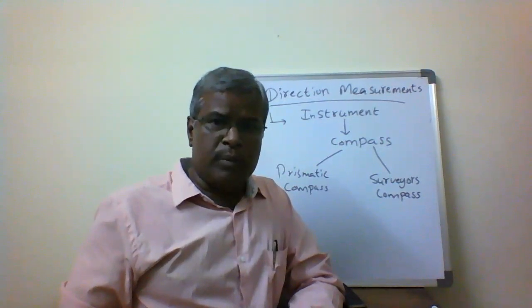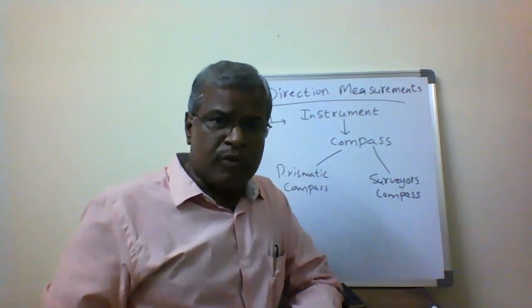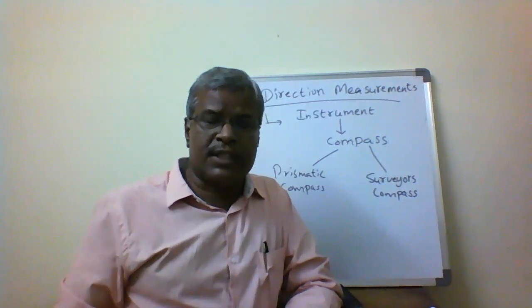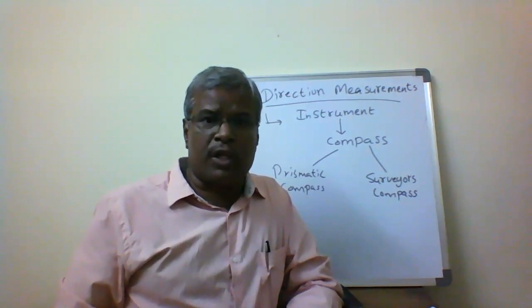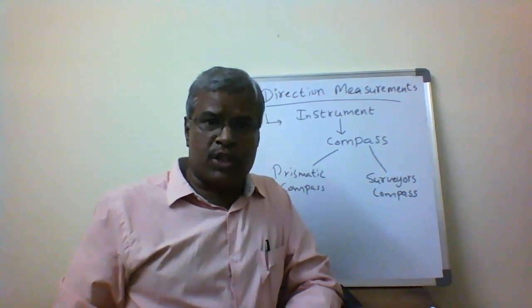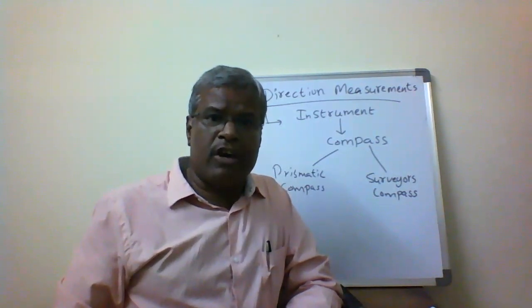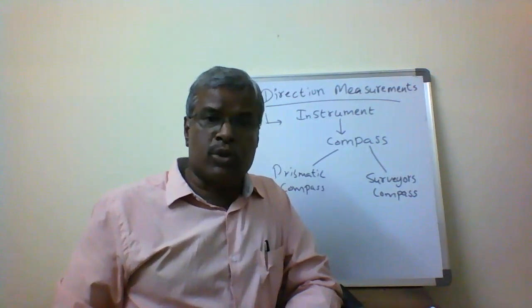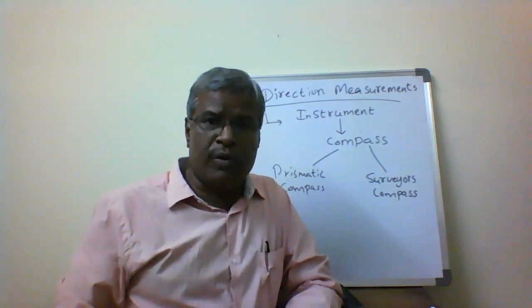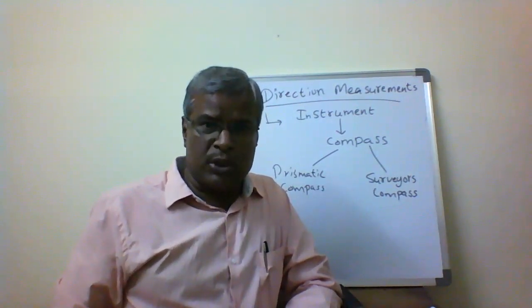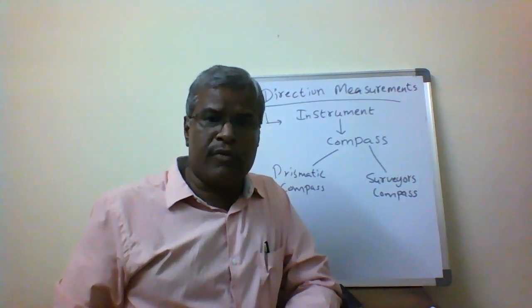Now we'll go one by one through compass surveying. We prefer to use it for a large area to be surveyed. Previously we discussed chain surveying. Chain surveying is used for smaller boundaries with no disturbances, because the instruments are just a chain and tape, and it suits flat terrain. If you go for larger boundaries, then in addition to the linear measurement by tape, we also need the angular measurements. That is the indirect way of getting angular measurements, from compass surveying.